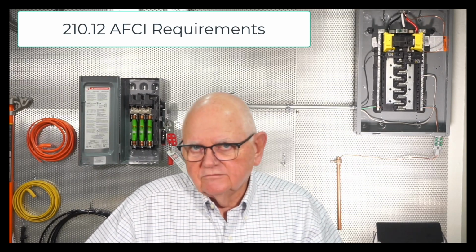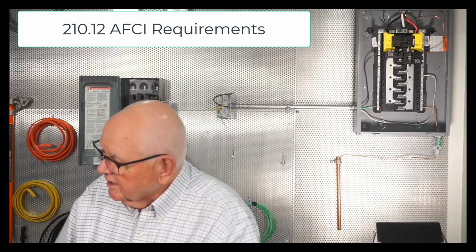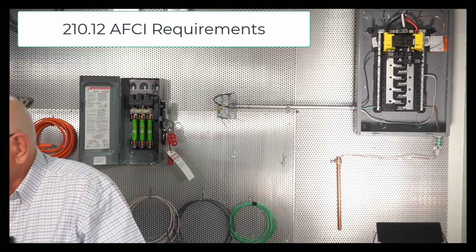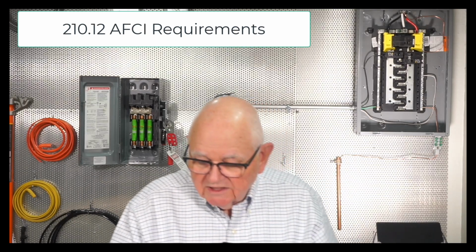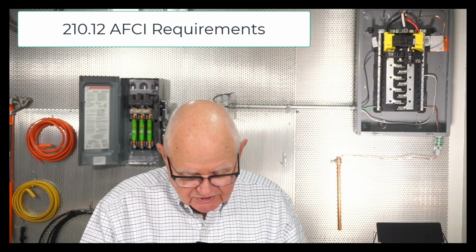So don't get confused here and think, oh, a combination AFCI also includes a GFCI. I've heard that misconception out there in the field, and don't do that. So anyway, 210.12 talks about where they are required. If you go through and read 210.12, you're going to find, in dwelling units, okay? First we take a look at the requirements for dwelling units. And what we're going to find is a list of 14 different items.